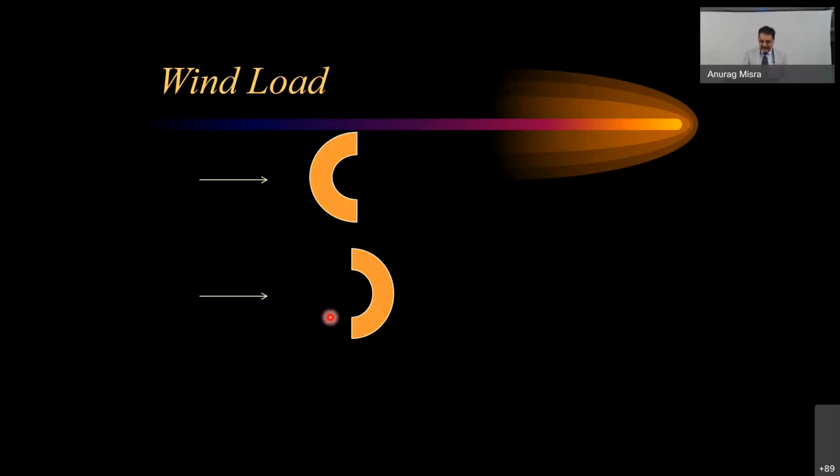So I don't want to discuss this design completely here, but with these examples, what I'm trying to just give you a flavor of what are the areas we have to be very careful while taking the force coefficient, because ultimately your design is going to depend on that. So if you have a concave shaped component, there's lots of pressure is going to be created from that side, and designers have to actually envisage that and take into consideration while designing them.